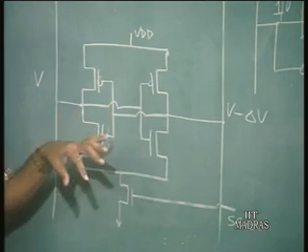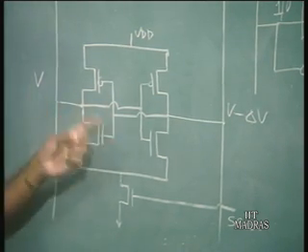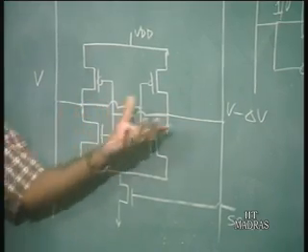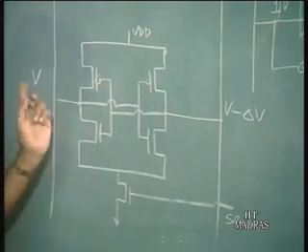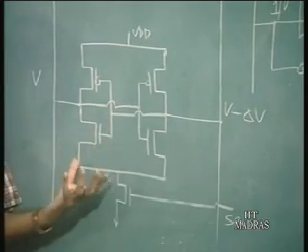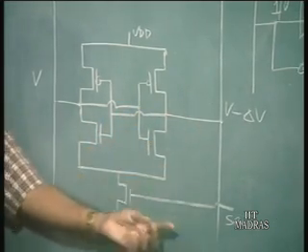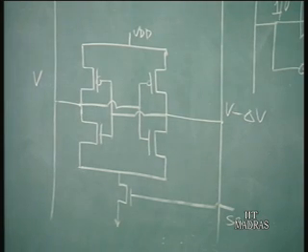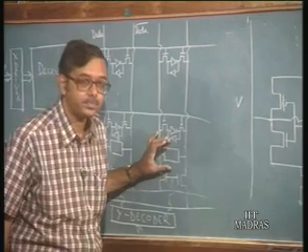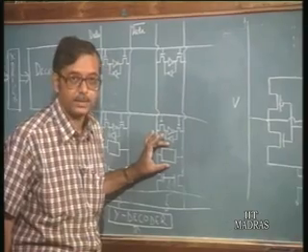So, because of the large positive feedback in this circuit, any discrepancy between the two voltages is going to be magnified or amplified, and so one line will go to 0 and the other line will go to 1, and this configuration will go to one of its two possible steady states. So, this sense amplifier is included in this cell here.